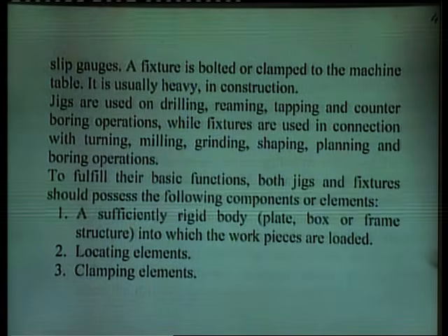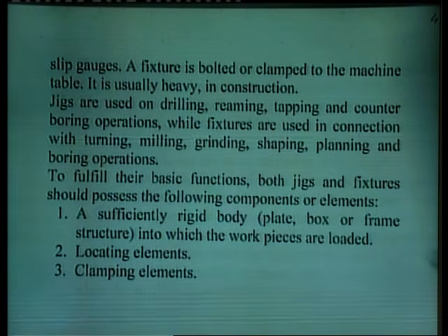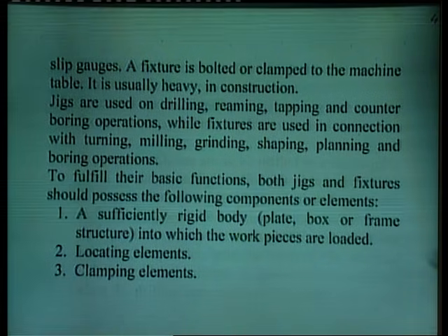Jigs are used on drilling, reaming, tapping and counter boring operations, while fixtures are used in connection with turning, milling, grinding, shaping, planing and boring operations.